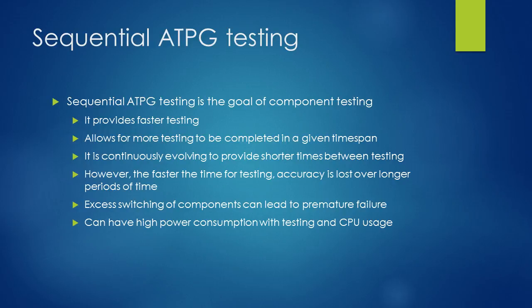Another downside is the high power consumption with testing because of the switching, and also high CPU usage of the computer, which can lead to lengthier times and also heat production, not just in the CPU, but when it comes to power consumption, you also generate heat in the die and socket of the material you're testing, and this heat also leads to potential thermal breakdown.